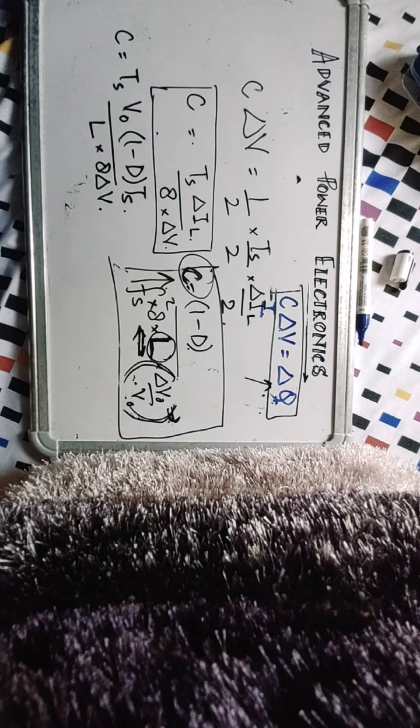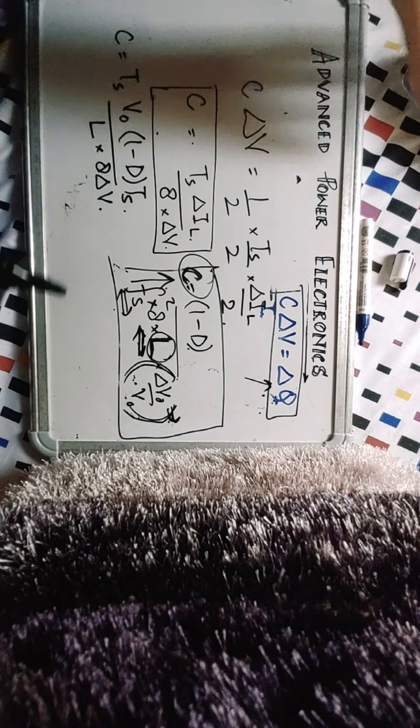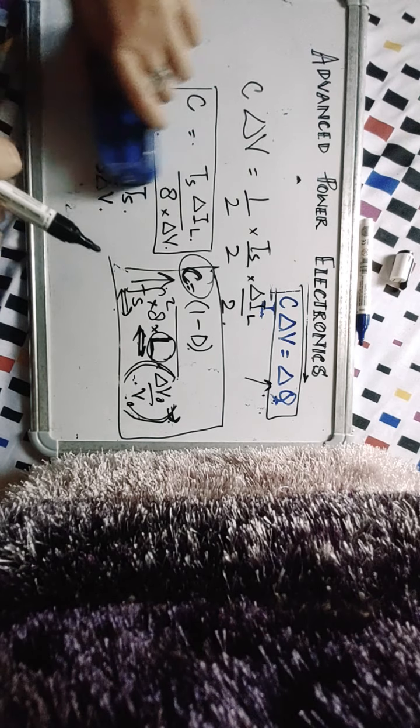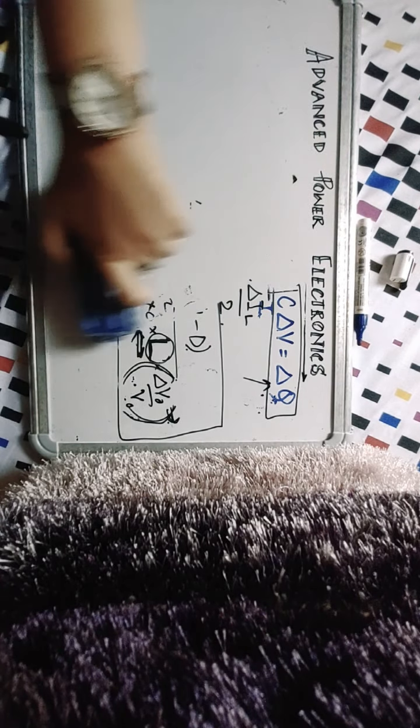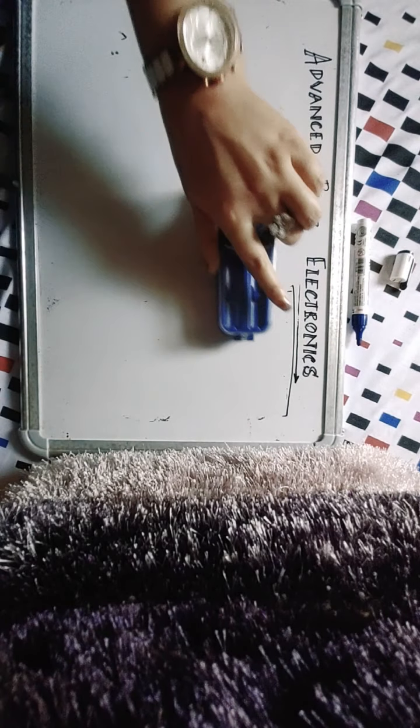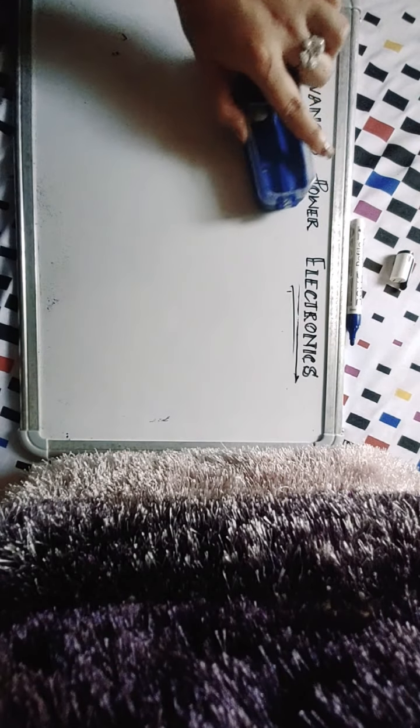So they're all interrelated, and the basic essence of this design is that higher switching frequencies will always tend to reduce the size of your passives, and that will make your circuit very small. And that is why DC to DC converters use high switching frequency devices, especially MOSFETs, and nowadays silicon carbide MOSFETs, SiC MOSFETs, because they can be switched at very, very high frequencies.